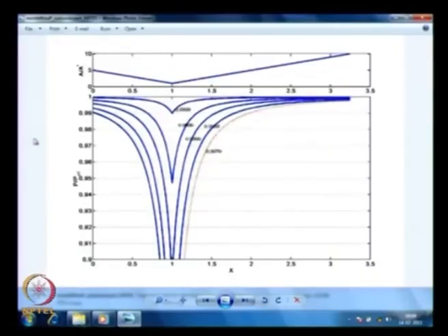I am showing here the nozzle for which I have calculated the pressures. I am showing you A by A star, where star is the throat condition, where it is 1. A by A star is 1 at this location. This number does not mean anything really, the x axis is just some distance. You are going to see that it starts from A by A star of 5, goes to 1, and then goes back to 10 at some location.